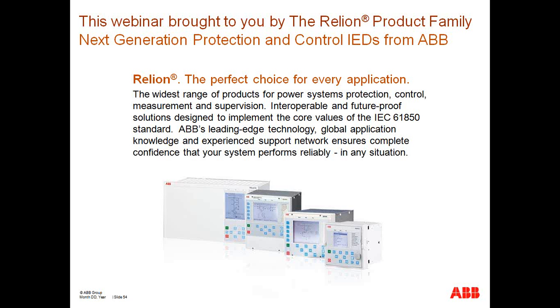One question that I have here is: the 61850 standard addresses asset management of electrical equipment. That's a very good question. What 61850 addresses is that it makes the information available, and it provides a data model that's standard enough that the manufacturers can make such information available. But 61850 at no point defines functionality such as algorithms to estimate the loss of life of a transformer. What 61850 would do for you is make the information that you need to run that algorithm available.